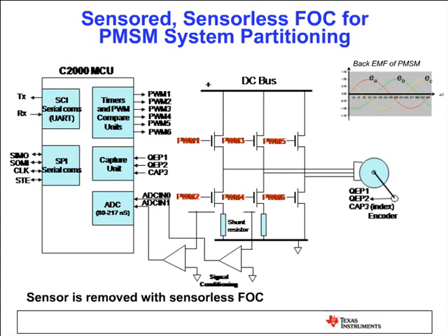And when you look at the graph window while spinning the motor, you don't see those pulses. What you see is a nice pure sine waveform without any kind of noise. And typically C2000 controllers are very fast, and they convert the signal in between 80 nanoseconds to 250 nanoseconds typically.